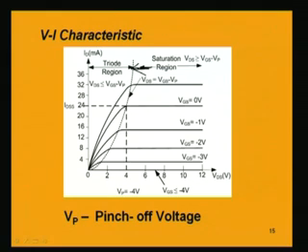And here also it reminds you of the depletion type MOSFET. There, the condition for the saturation of the drain to source current was when the drain to source voltage was greater than the gate to source voltage minus the threshold voltage, and that threshold voltage has a counterpart here, which is the pinch off voltage. Otherwise it is the same characteristic.